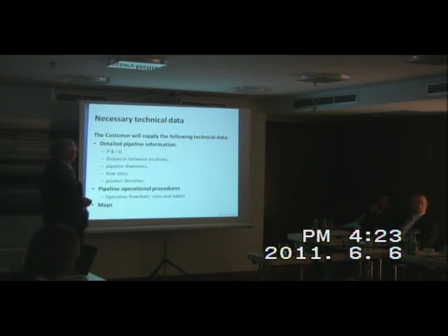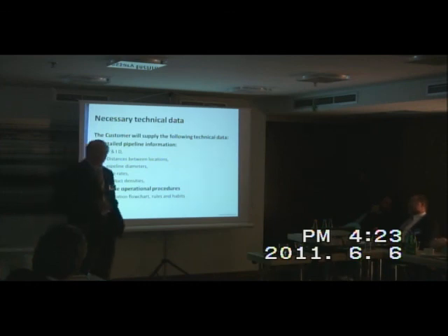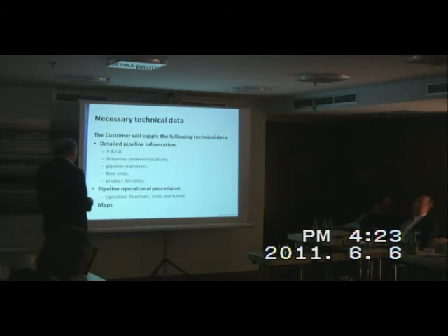We also need to know the pipeline diameters, the flow rates, and the product density. This is the basic information I need. And also the procedures, a description of the operations, how the operator works with this pipeline, and if possible the maps of the pipeline.